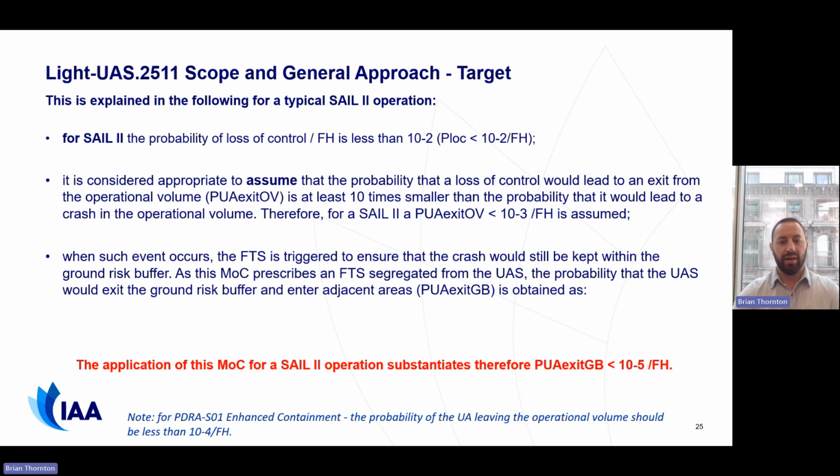When such events occur, the flight termination system is triggered to ensure that the crash would still be kept within the ground risk buffer. As MOC 2511 prescribes, for an FTS segregated from the UAS, the probability that the UAS would exit the ground risk buffer and enter the adjacent area or adjacent airspace is obtained as follows.